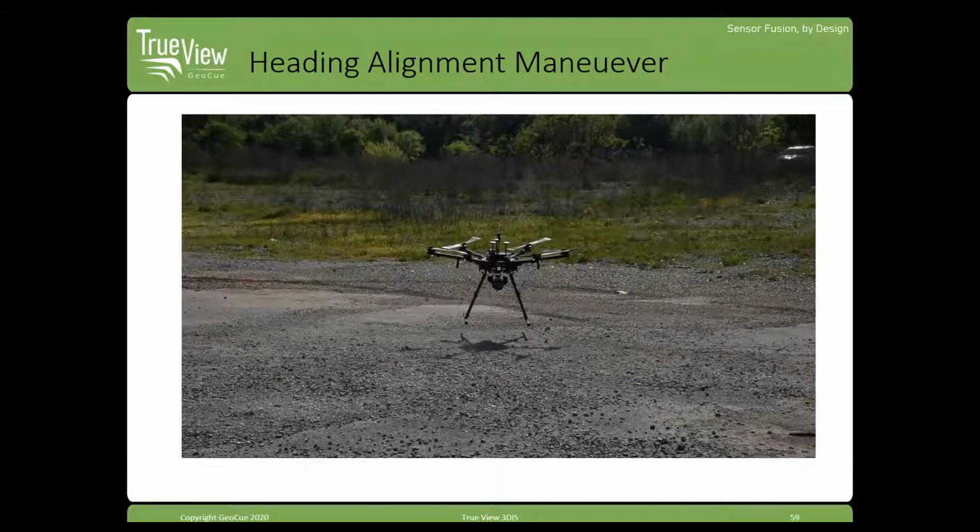What we're gonna want to do is, typically what I'll do with the power on the drone, something I didn't mention, is I'll either wait until the LIDAR is completely ready to go, or I'll wait till after the GNSS is acquired, then turn on the drone. You of course can turn it on beforehand, but it just kind of saves battery on the drone. But whenever you're ready to take off, you'll take off manually.